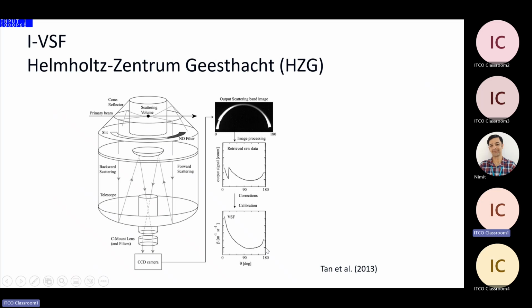But when you see stuff like this big tail up on the back end, what happens when you have samples that are enclosed in a volume is that it's very, very difficult, when you pass light through it, not to get residual reflections in that tube, in that container. And there are actually some of these sensors, which I'll show you, that go to extreme measures to try to avoid those reflections. But this is a good example here on the end that there's probably some reflection within that tube.